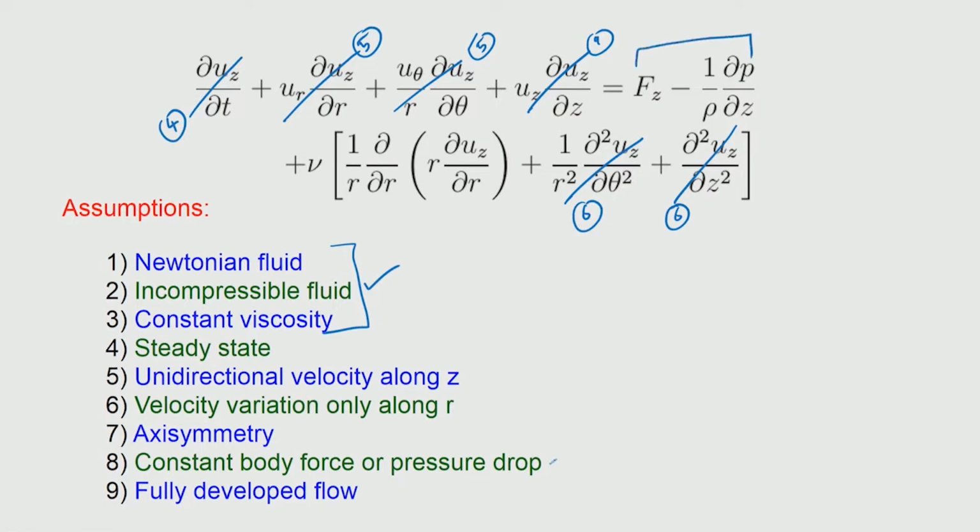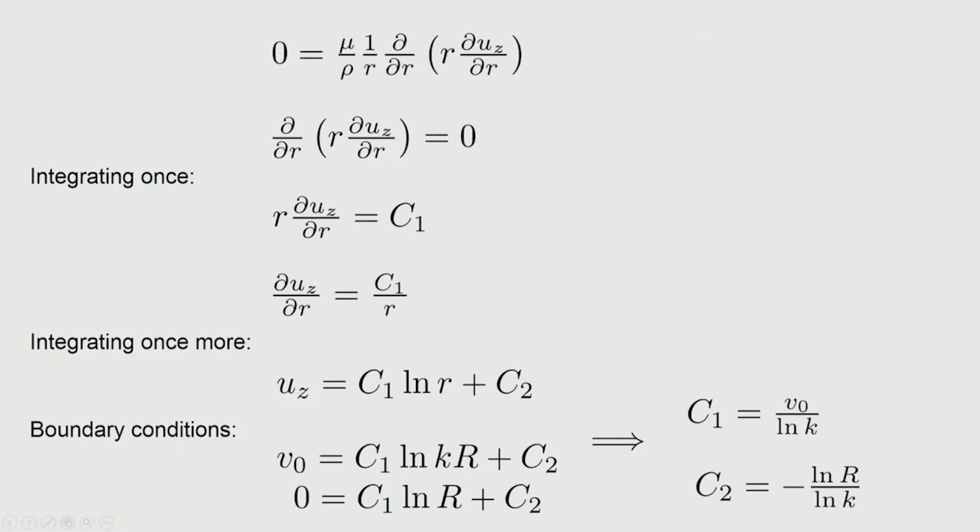Okay, so 0, because we say that the flow is because of only the boundary conditions and not because of anything else. So we just drop this, which leaves us only with these terms, and that term we basically write it, and this is now the trivialized form of the Navier-Stokes equation for the z component, and when we integrate twice, then we get the logarithmic term.